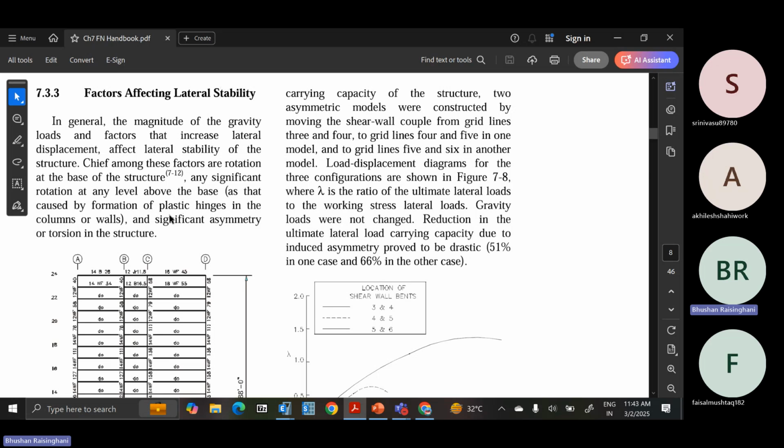That's why in performance-based design, when we do the pushover analysis, we consider that at the base of the building, it is okay if it is yielding, because we cannot control that yielding. Apart from that, any yielding of the column at the base in the above stories is prevented. So at the top and the bottom story, we cannot prevent the software from generating the hinges. However, in between, at each story bottom, the hinges should not form. That is the criteria, or the ideal situation that we assume for pushover analysis.